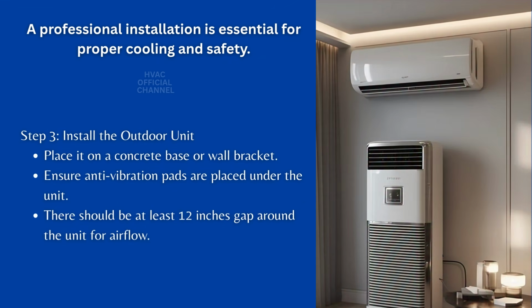Step 3. Install the outdoor unit. Place it on a concrete base or wall bracket. Ensure anti-vibration pads are placed under the unit. There should be at least 12 inches gap around the unit for airflow.